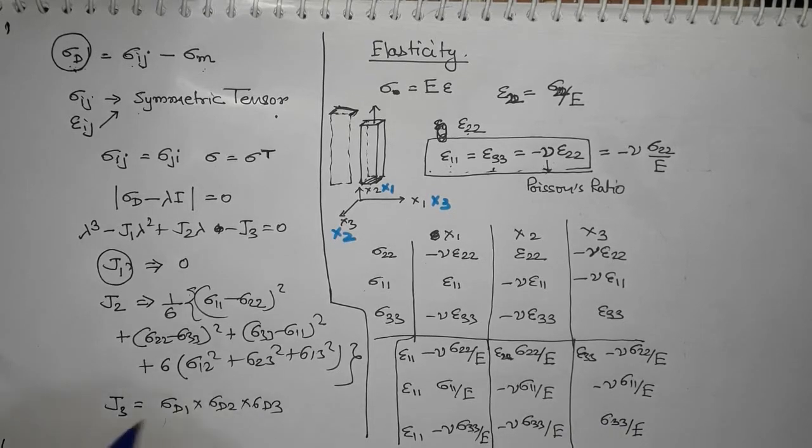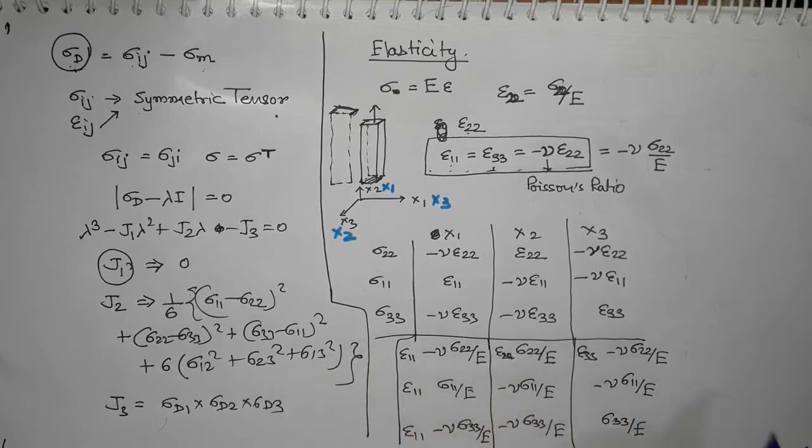Okay, and now, because we are talking about small strains and elastic deformation, we can assume that the normal stresses in one direction are not influencing the stresses in other directions. We also assume that shear stresses are not contributing to the normal stresses, and these are the assumptions which we make in order to apply the superposition.